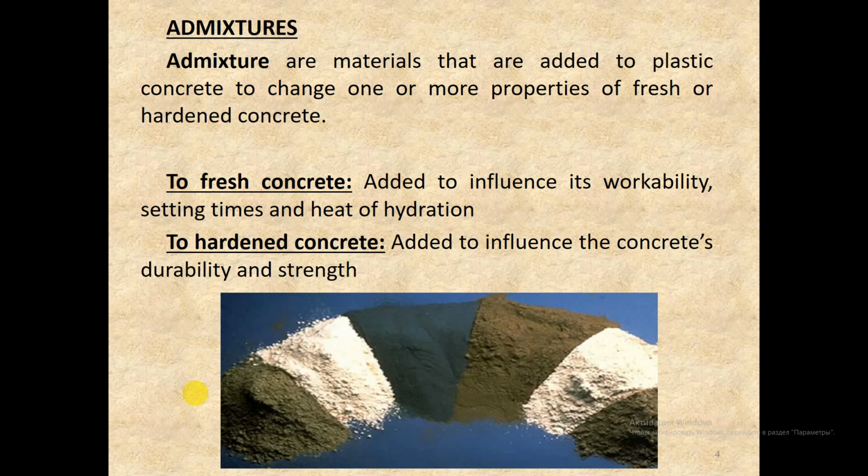Because admixtures are added to concrete mixes in small quantities, their inclusion should be carefully managed. Incorrect dosage of an admixture, either too much or too little, may adversely affect the strength and other properties of the concrete.